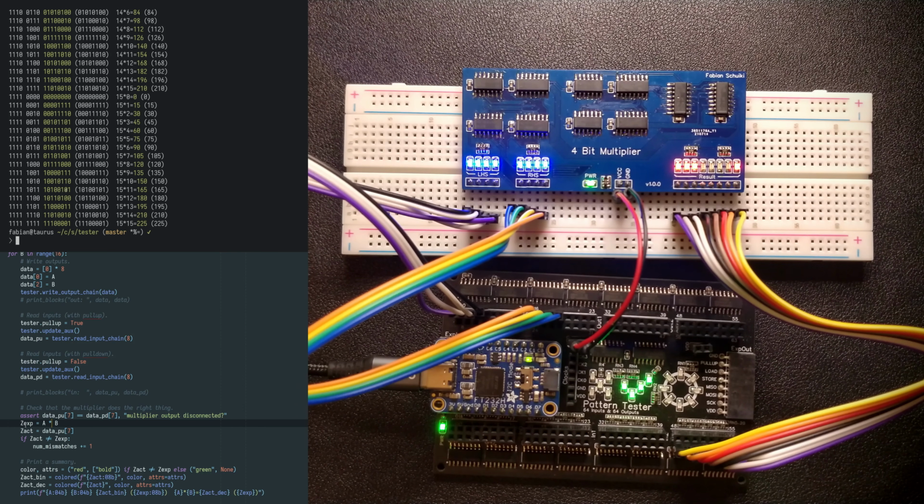And we have a model somewhere in software, for example, written in Python, like we did the A times B here. We have such a model, and what we do is we feed these random inputs that we've picked to the hardware and read back the result. And we also feed it to this Python model that we have and look at what it thinks the hardware should produce. And then we compare the two, and that's going to indicate if our hardware does the right thing or not.